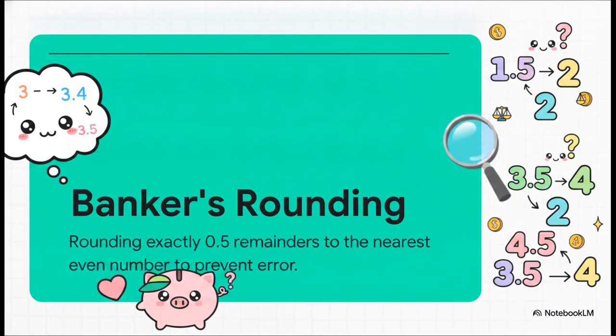Converting these highly precise fixed-point numbers to fit back into smaller hardware spaces presents a massive challenge. Say a calculation results in a fraction, like 3.5, but you need to turn it into an integer. If you always just truncate and round down to 3, or always default to rounding up to 4, you are going to cause massive, system-breaking error accumulation over thousands of AI calculations.